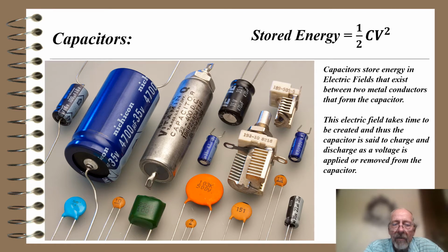If we take a look at these very colorful capacitors on the left-hand side, there are electrolytic capacitors. The big fat ones are electrolytics. There are many different other shapes, and there are actually some variable capacitors there where air is the insulation between the conductors that make up the capacitor. And the plates mesh with one another, but they don't touch.